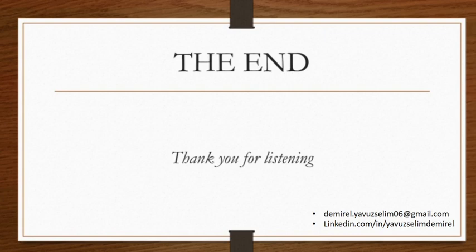To sum up, in this chapter we discussed the rock cycle, the origin of soil by weathering, the particle size distribution in a soil mass, the shape of particles, and clay minerals. Some important points include the following. Rocks can be classified into three basic categories: igneous, sedimentary, and metamorphic. Soil is formed by chemical and mechanical weathering of rock, and based on particle size, soil can be classified as gravel, sand, silt, or clay.